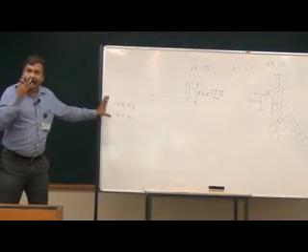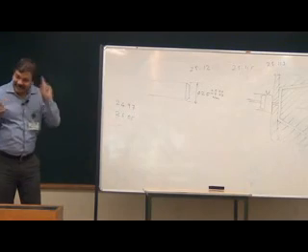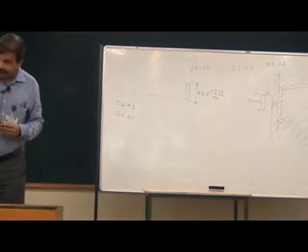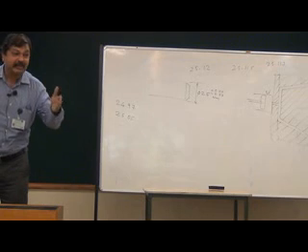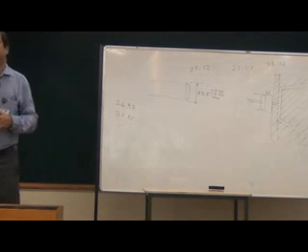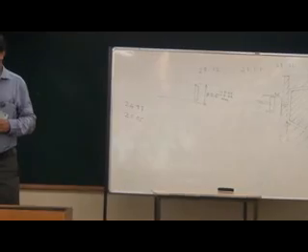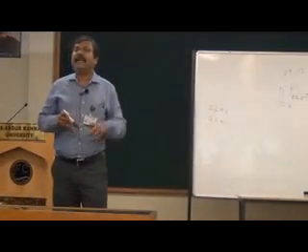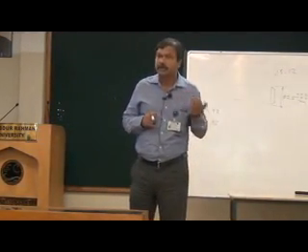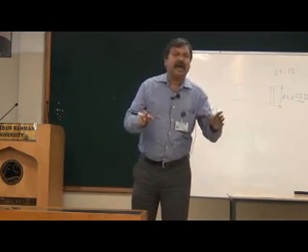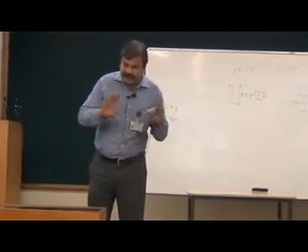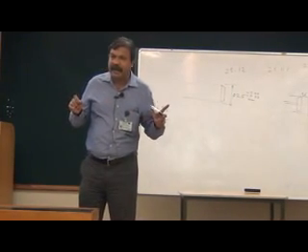So here I am not specifying a single value, but rather a range of values. This is called tolerancing. What is tolerancing? I tolerate variation. Why do I tolerate variation? Because nature doesn't permit things to be identical.